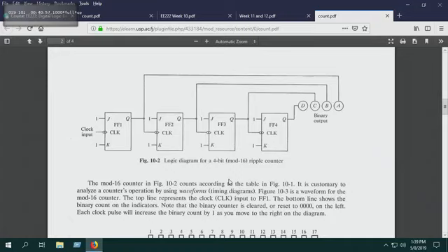In asynchronous counters we want to use either JK or T flip-flops. Because in JK, what happens? Remember I showed you the theory, a step-by-step explanation of JK. Go on, tell me, what happens to Q? It toggles. So if one round it shows a 1, the other round it will show a 0.